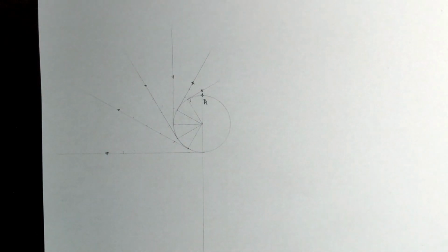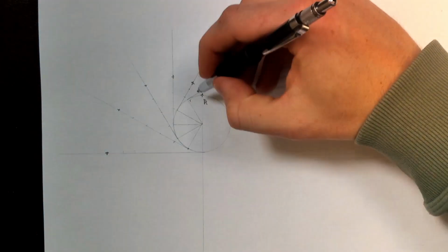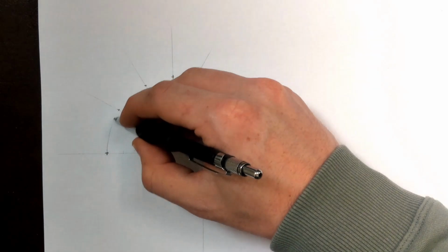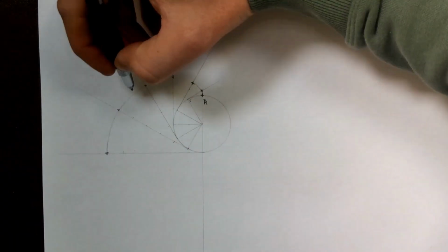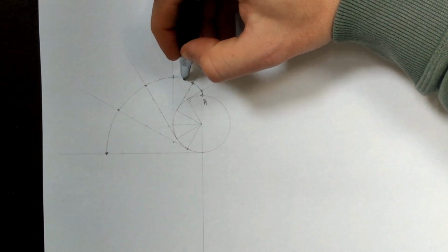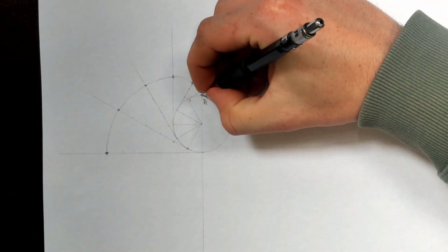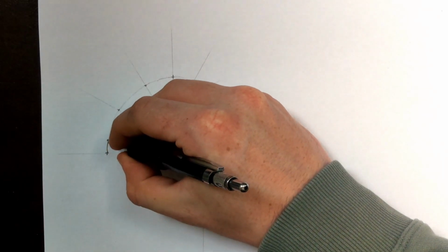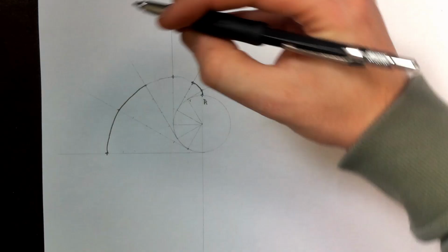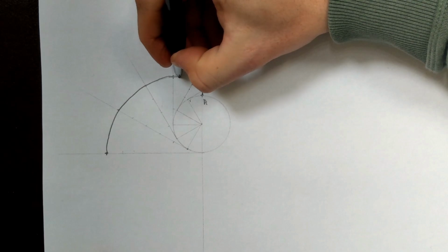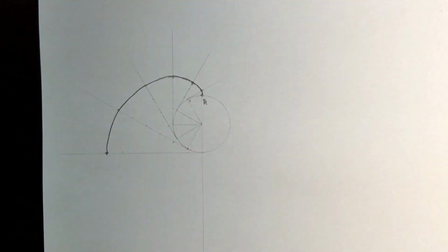Okay, so that is the involute. It's a fairly simple thing to do, and it's drawn freehand. The involute of squares and triangles, anything that has straight lines, is actually done with the compass. So you swing them with the compass. But when it comes to circular things and circular sections of involute, you draw them freehand like this. Okay, so there's that part.